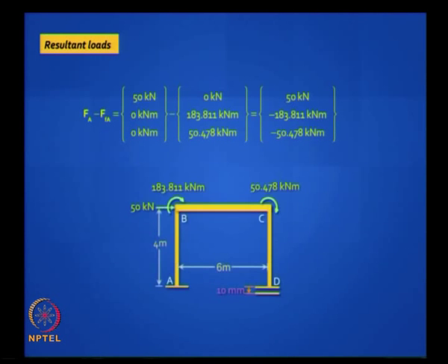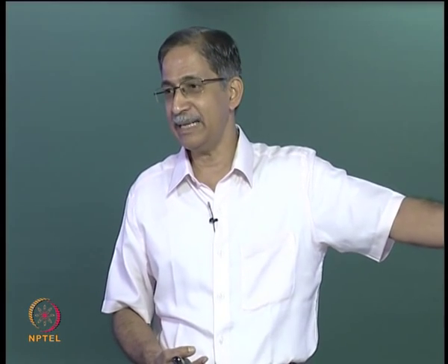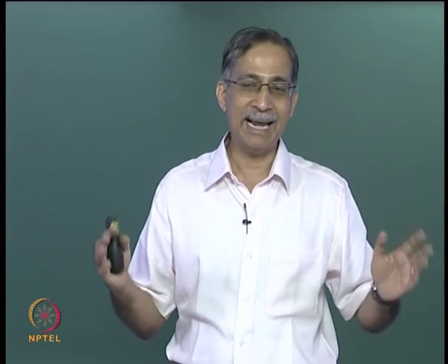Okay, and here you do not worry about those concentrated loads as we did earlier, because they are not going to affect the displacements because they are actually rigid. So even if I put them, it is not going to make any difference. It is not going to cause any actual difference. Is it clear? So I do not even need to do that exercise, and so this is identical to slope deflection method, but you made an assumption. Assumption is actual deformations are negligible. How true that is for this problem we will know shortly.